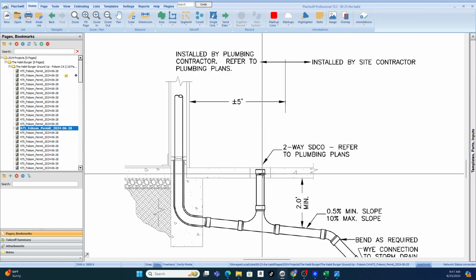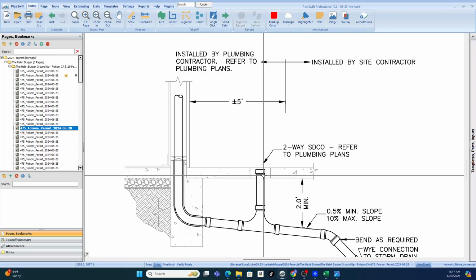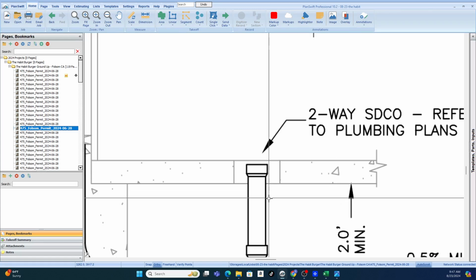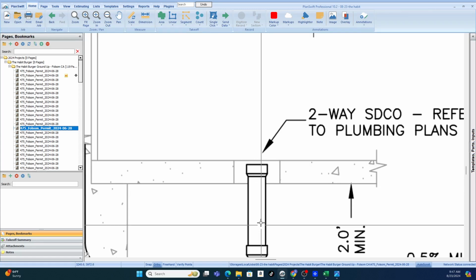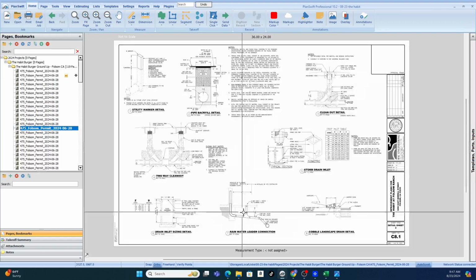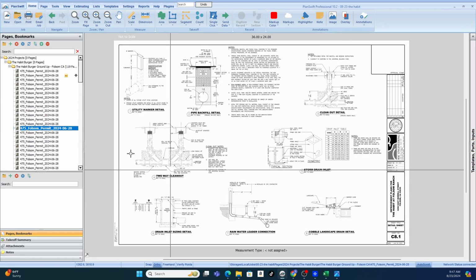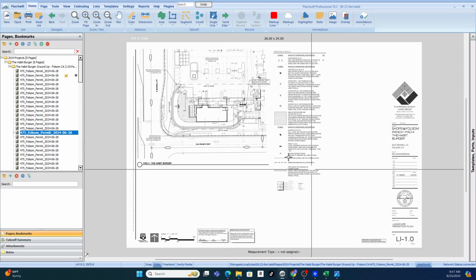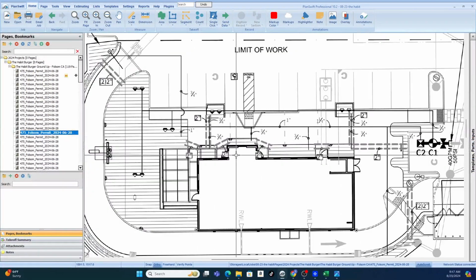Okay, and if you've got six clean outs, you got to have 6 times 10. Six of these times the additional vertical measure. So never forget that, or you'll be the lowest bidder unnecessarily. So okay, and then we'll go over the landscape plan.